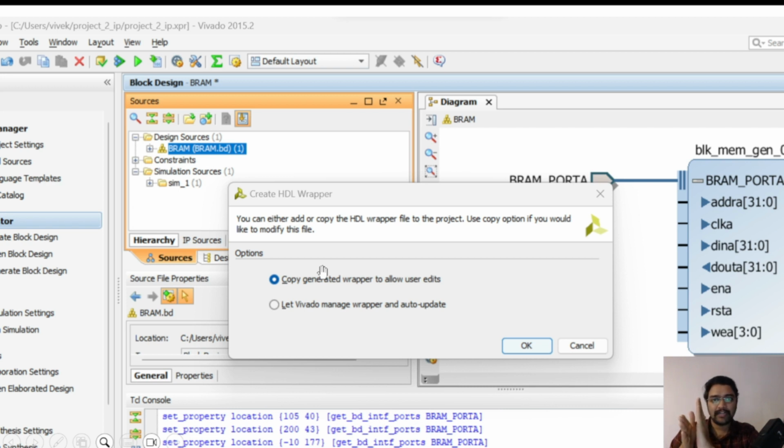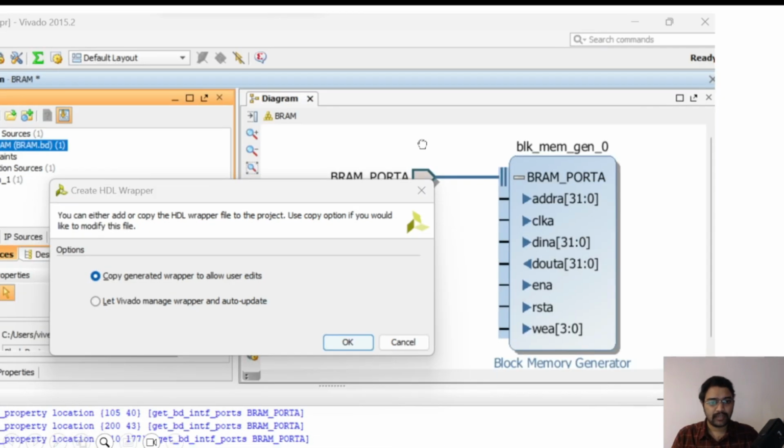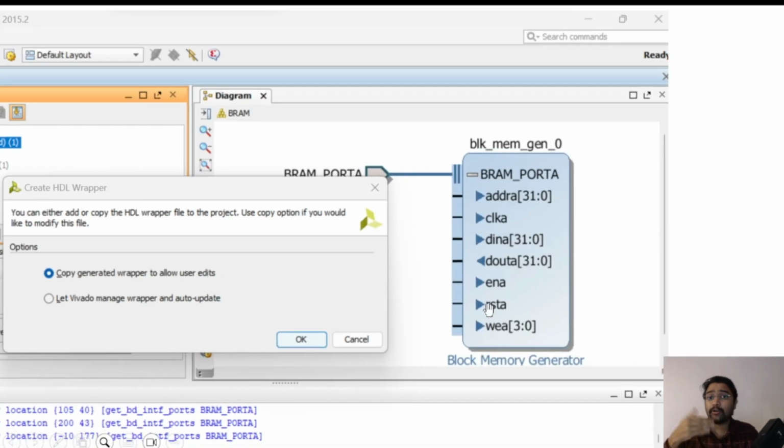Now you have designed input pins, output pins, and so on. You have designed all these things on your own by the specification. When you selected the IP, right, this comes with this. But you can also alter the design. And when you design all these pins, these should be declared in the VHDL script. That is the reason they made a draft. When you click on generate HDL script, from the draft, it will assign all these pins.